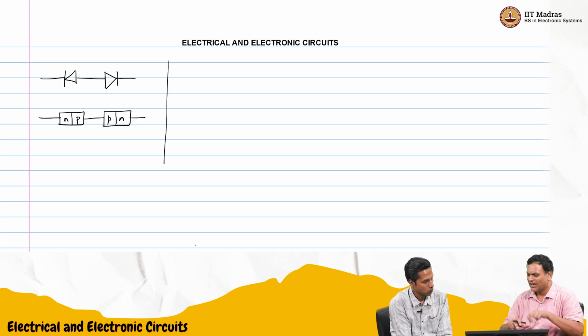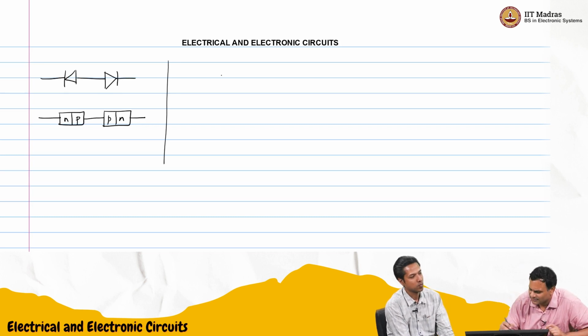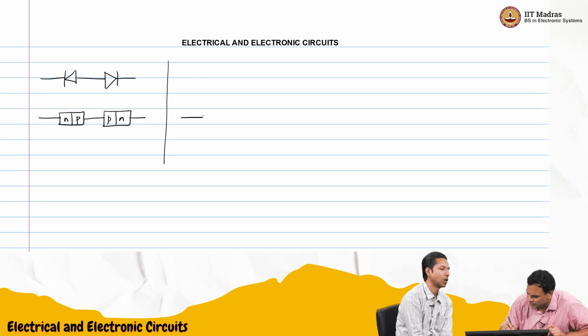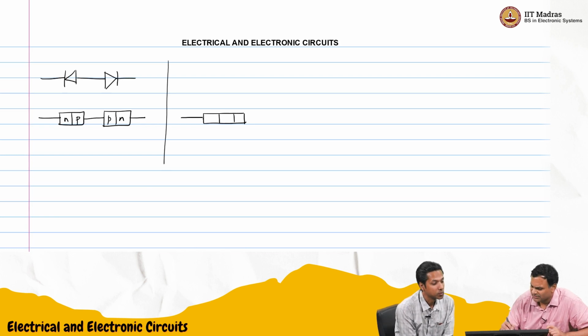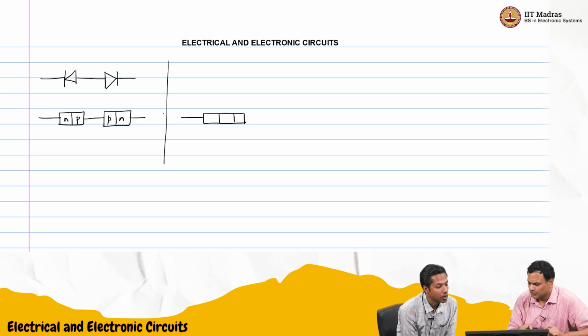So maybe what I need to do, instead of connecting two junctions by a wire, is just fuse them. I have two P types. I can just make it one long P type. So I'll just do this. This is in the fabrication step itself, a different process. So I'll make it like this. I'm going to combine these two and just put one P there.